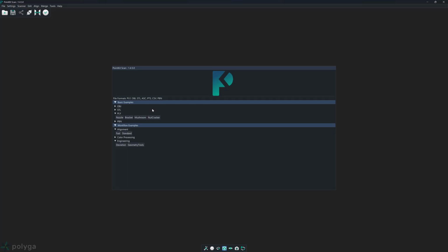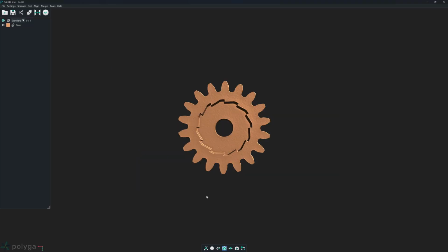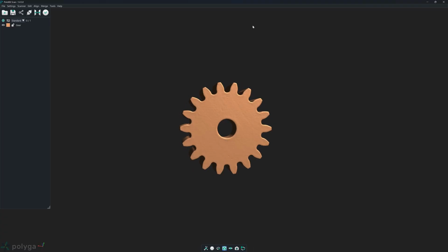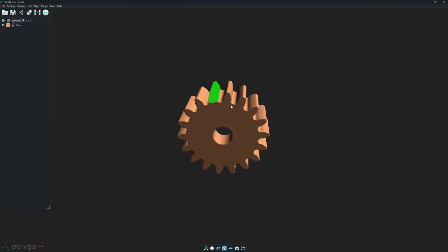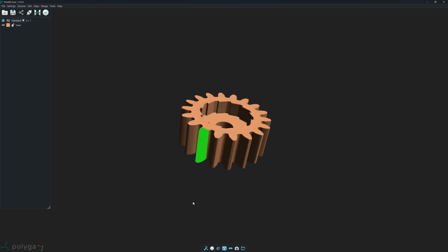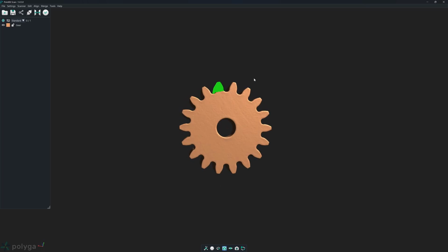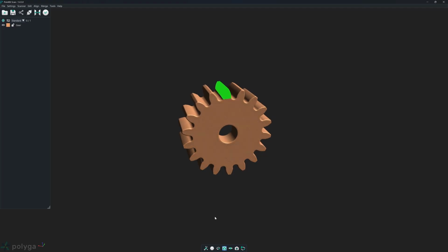Next, we'll show how to select different regions of your mesh. I'll load up the Geometry Tools example for this. By default, we have our Lasso tool, and we have Select Through disabled. Our Lasso tool is pretty straightforward. We can select different regions of our data. When Select Through is enabled, all vertices that correspond to our lasso in screen space get selected.